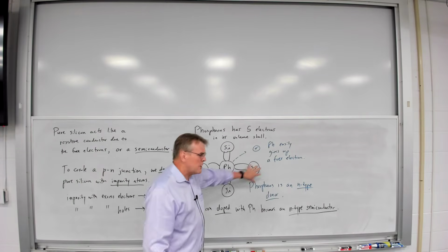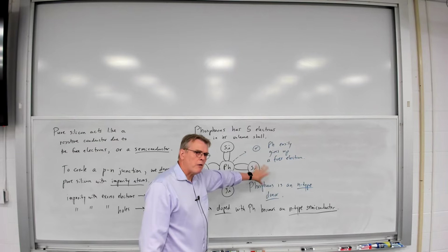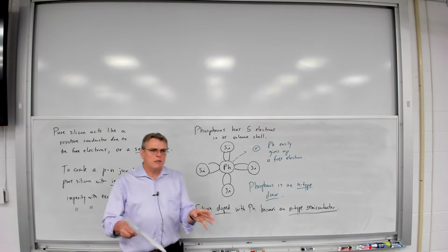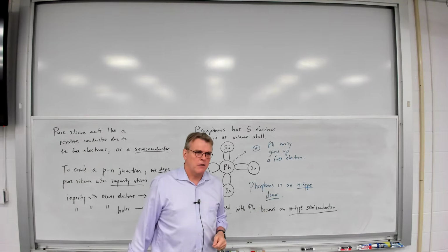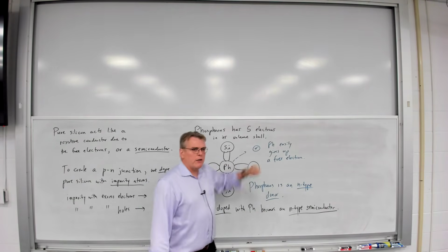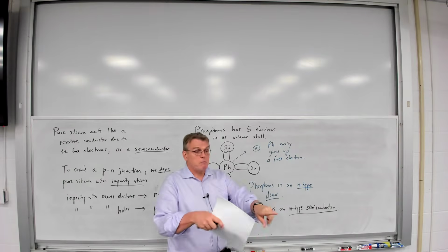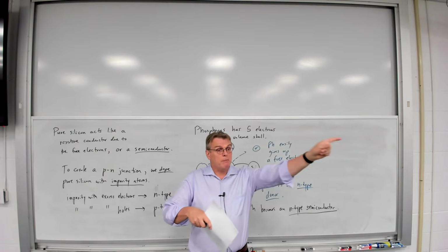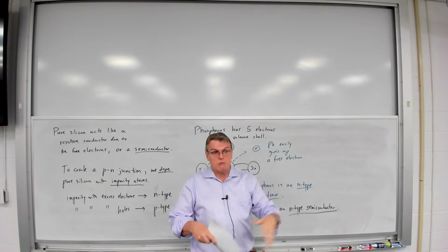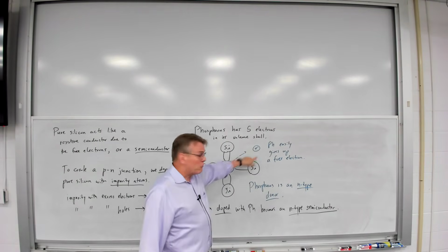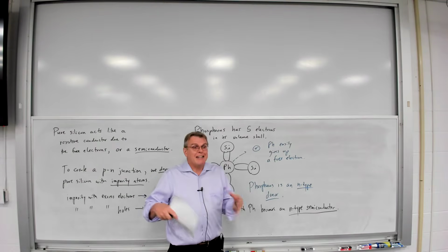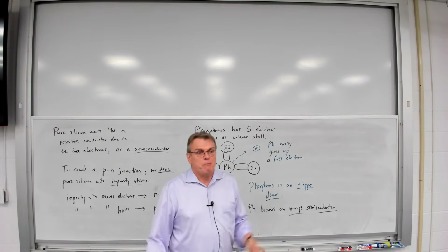Well, the silicon is always going to be forming the 4 covalent bonds with the other atoms around it. So all the silicon in the lattice is always going to want to form and keep 4 covalent bonds. So any extra free electrons drifting around, yes, there will be an occasional silicon atom that will give up an electron and then recapture it just from thermal energy like we talked about before. But these electrons that are given up by phosphorus generate, in effect, excess carriers that nobody wants.